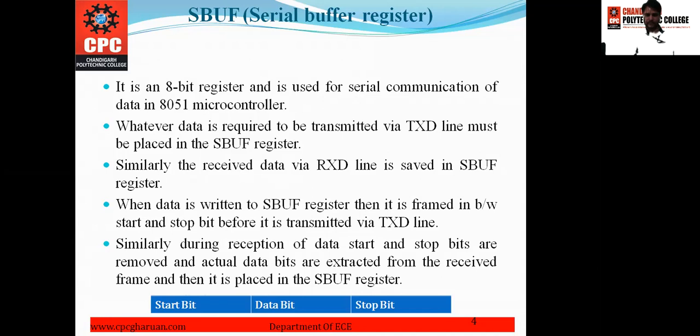Whatever data is to be transmitted by the TxD line in 8051 must be placed in the SBUF register. Similarly, at the receiver end, the data received via the RxD line is saved in the SBUF register.